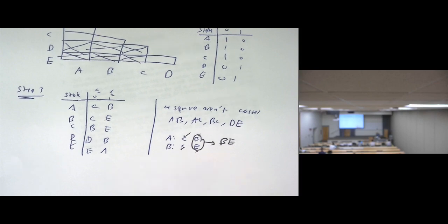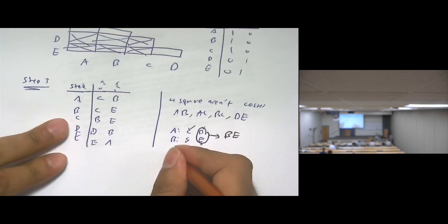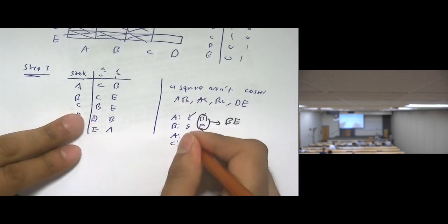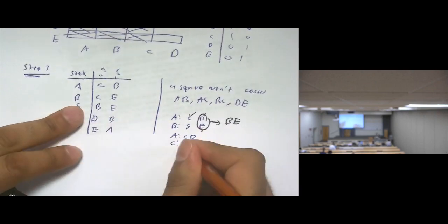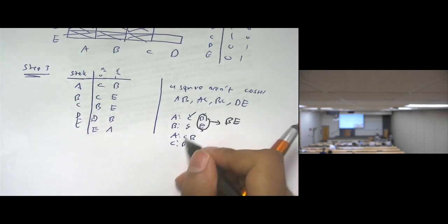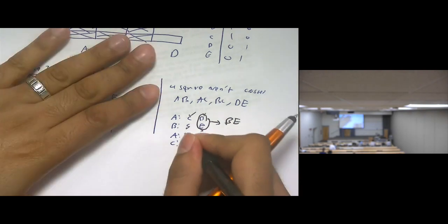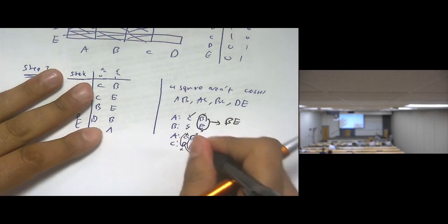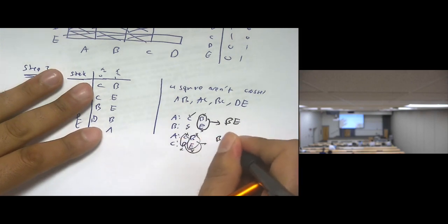How about the next, which is AC? A and C. A will give us CB, C will give us BE. So here, those are not the same, right? They are different here and different here, right? So take them as a column and write them in alphabetical order. So the implication pairs are two, which are BC and BE.